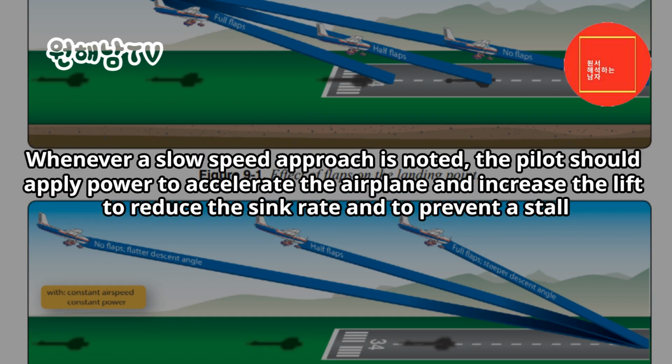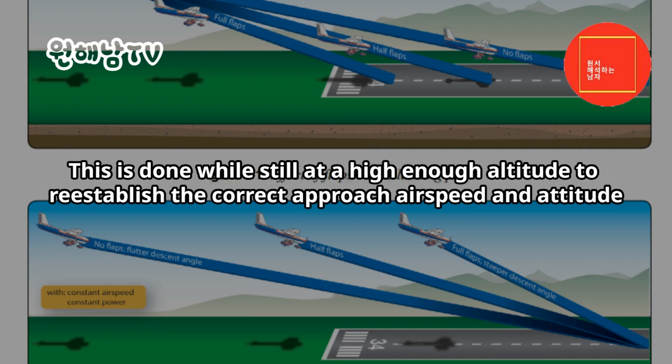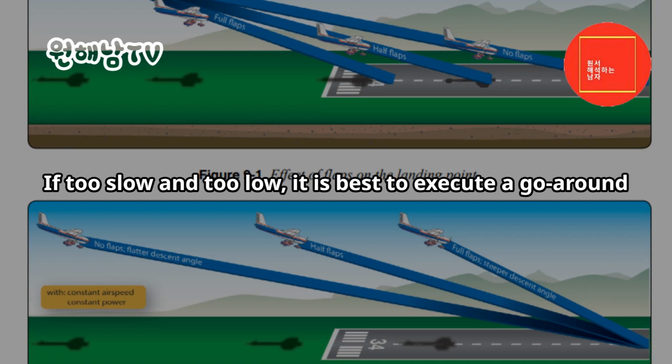Whenever a slow-speed approach is noted, the pilot should apply power to accelerate the airplane, and increase the lift to reduce the sink rate and to prevent a stall. This is done while still at a high enough altitude to re-establish the correct approach airspeed and attitude. If too slow and too low, it is best to execute a go-around.